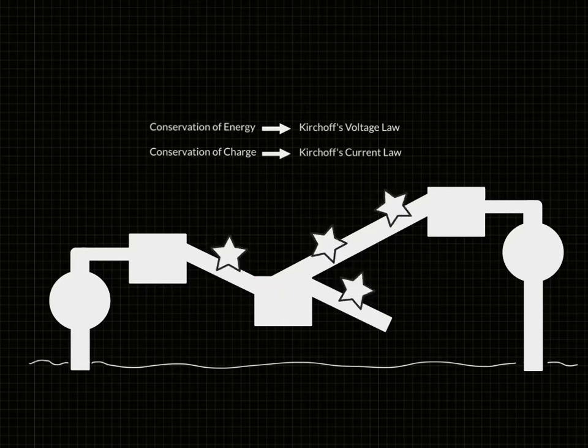That's simple enough. Conservation of charge is saying that any amount of current that flows in any of these regions can't build up in any one of these regions. It can't store any more than is allowed to flow. So if something's flowing here, something's flowing here, then that same amount, these two added together, must flow out. So whatever's in goes out, obviously. Otherwise you're building up. It's conservation of charge.